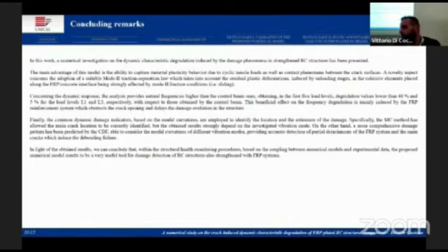In conclusion, we proposed a numerical model that, with a proper calibration of some parameters, is able to take into account all the typical nonlinear phenomena induced by cyclic loading conditions, which are the loading conditions really present in existing structures. In light of the obtained results, we can conclude that our numerical model could be a useful tool for damage detection in a reinforced concrete structure, also strengthened with FRP.